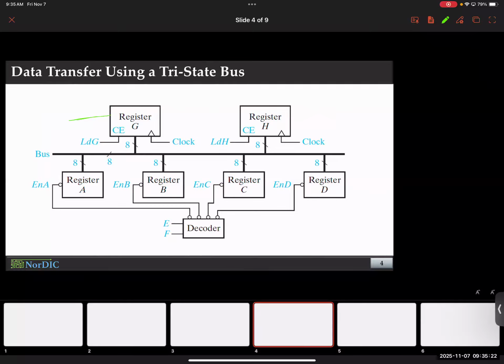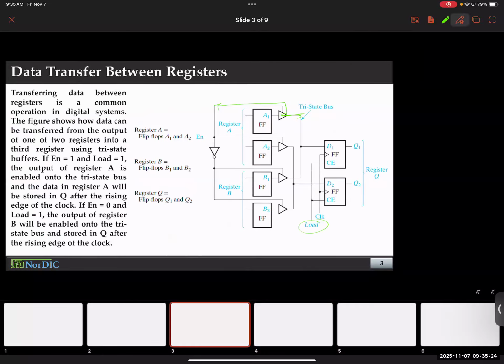So even if you disable the register, it basically represents that its output will not be sent for that cycle. But as long as you keep your load signal activated, it will still be loaded. It will not be sent to the next level, but it will still be loaded. Because who determines the loading operation? Clock.